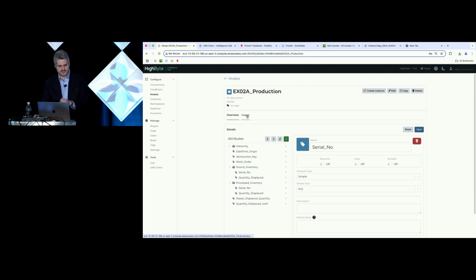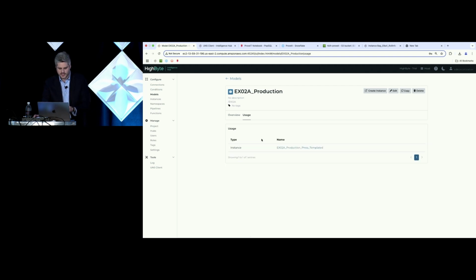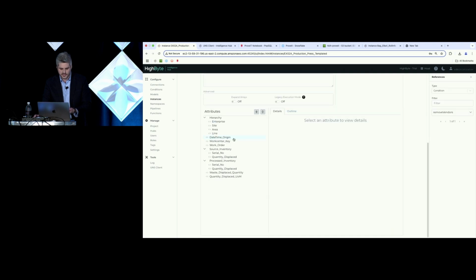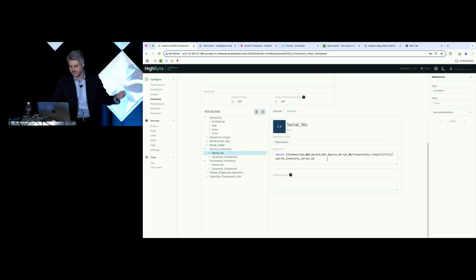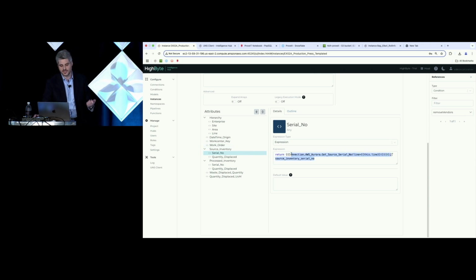So what I wanted to say is this could look like the shape of what a MES API would want, right? So essentially what I'm doing here is I'm taking transactional data. For example, my serial number is probably not going to be inside of my PLCs, right? I may actually need to connect to an MES system, right? However, it might be useful for me to use master data to evaluate that. Or I might have telemetry data, right? So I might want to cross-reference values and such.